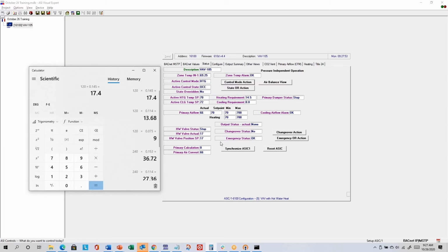Every time it goes into deadband, it will drive closed for an additional base time to make sure that it is fully closed. If you've worked with tri-state or floating equipment before, you might have seen that you can lose fractions of a second as you change directions back and forth. So it's good to reset the 0 position so that the controller and the actual field device are in sync. So that's how it works if you had a floating hot water valve actuator.